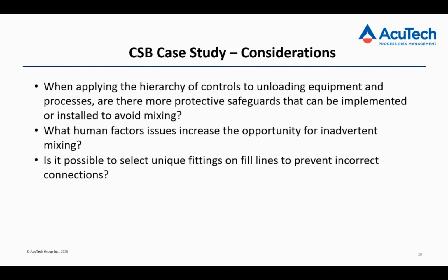However, I can tell you about an event I once investigated. A truck driver pulled up to the wrong tank at the plant. He found a different unloading fitting than what he was expecting, because the plant had taken some steps to put in unique fittings. Well, the truck driver had a box full of miscellaneous fittings in the cab of his truck. So he got out his box of fittings, and he was busy jury rigging a fitting that would work, when luckily an operator saw what was going on and came over and stopped him, kind of in the act. So even those unique fittings can be defeated.